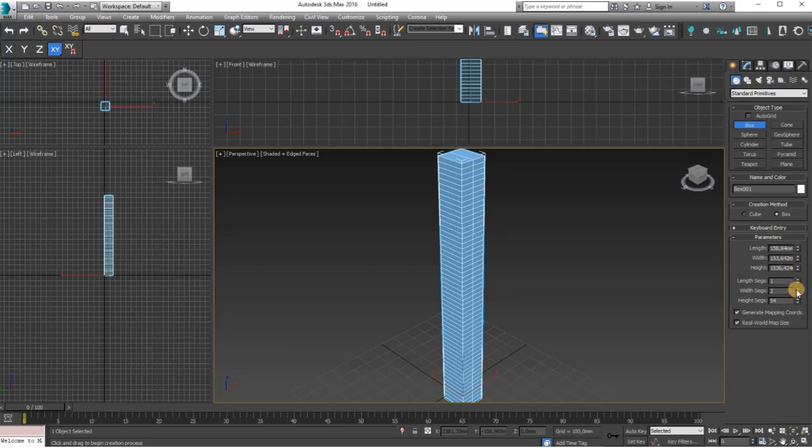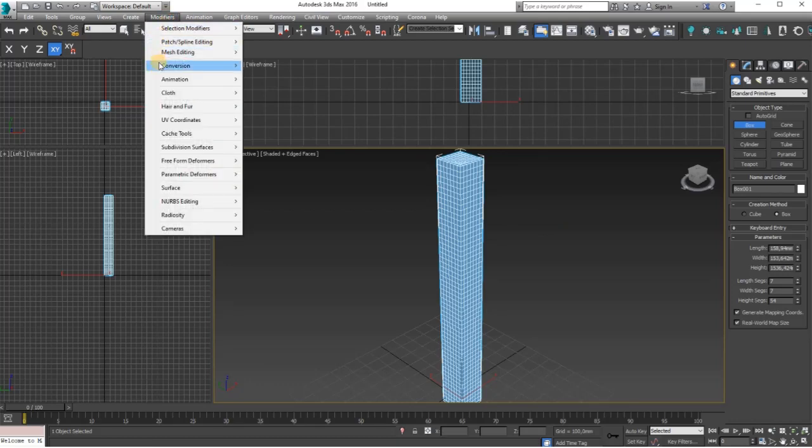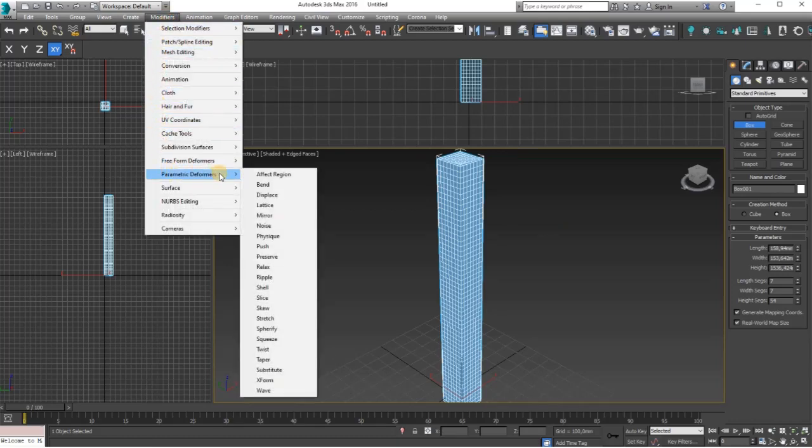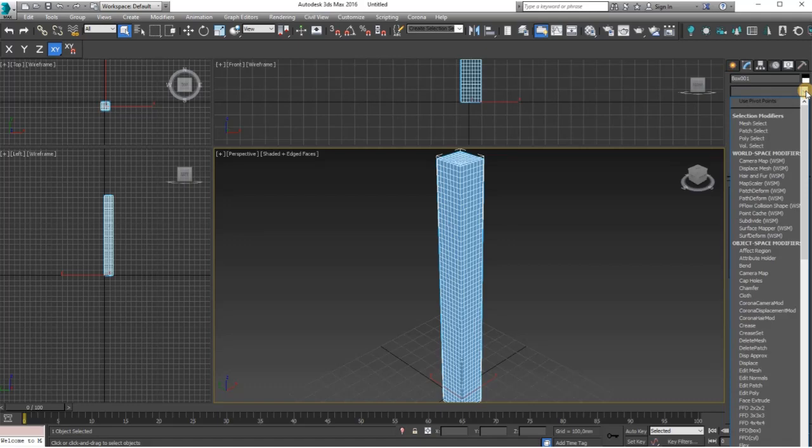Alternatively, you can select the object in the viewport and choose the Modify tab from the Command panel. The Modifier List drop-down list will be displayed. Select Object Space Modifiers, Bend from the Modifier List drop-down list. The Bend modifier will be displayed in the modifier stack. Also, the Parameters rollout will be displayed in the Modify panel. The areas in the Parameters rollout will be discussed next.